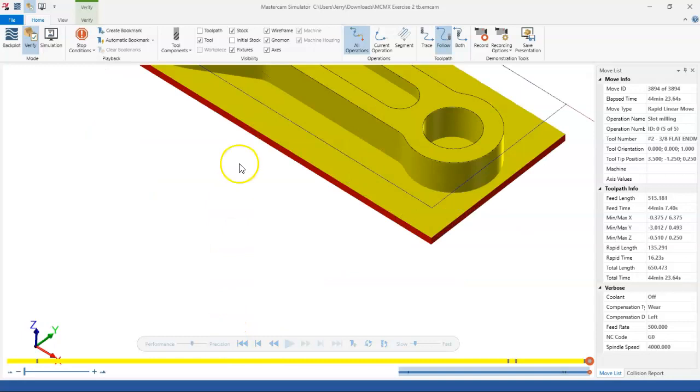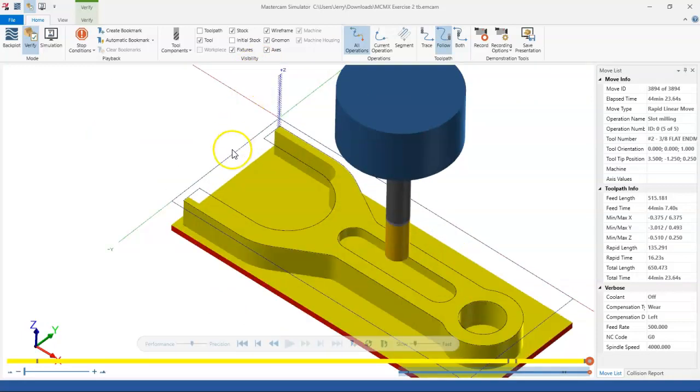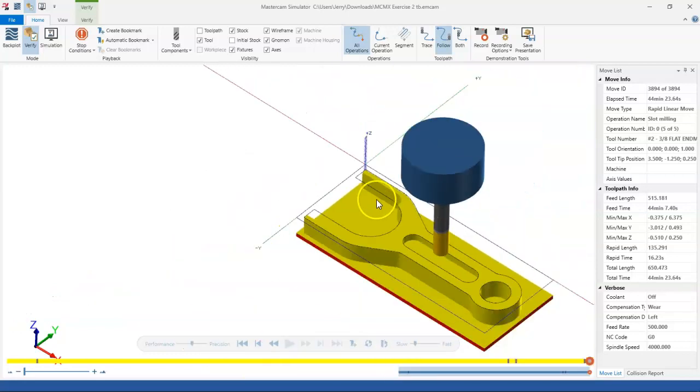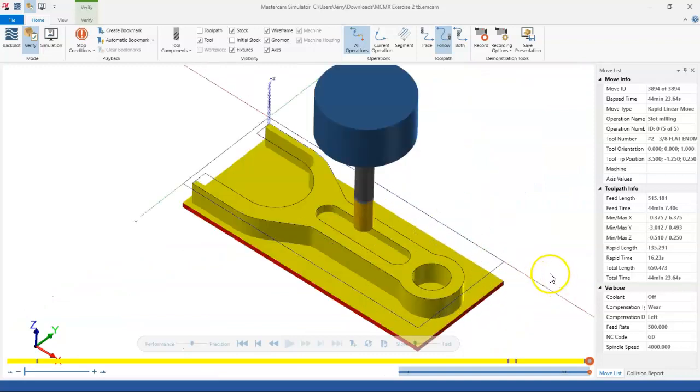There's the tool dugout on the top. Yep. Right. So that was the blend, and we were looking at that as going to the edges. If you don't catch it in the toolpath, looking at that operation, then the simulation should make it very apparent that, oh no, that's going to be bad. All right, so you're using all these tools, and that puts you up into 95% confidence. I go back and make this correction, run the simulation again, and take this out to the machine.